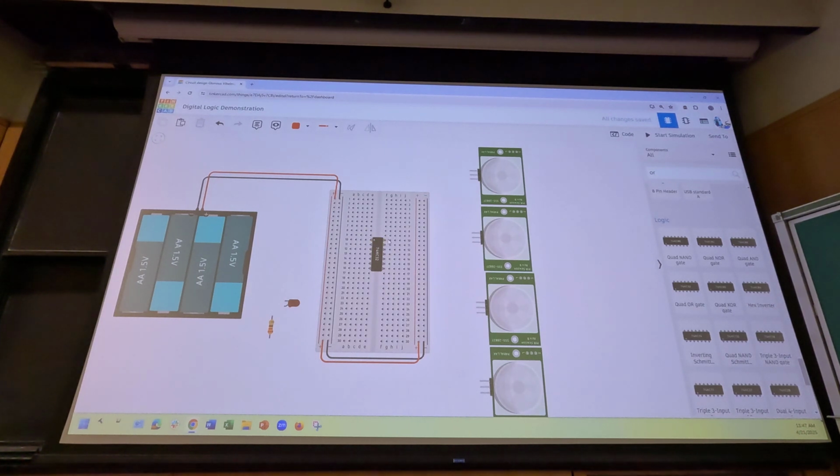So bare minimum, actually this is another one of the things I probably should have checked to make sure this chip will accept 6 volts as an input, but I think it's fine. Okay. Powering the chip doesn't make it explode. So bare minimum for starters, make sure you power the chip. It has those separate power and ground pins, and then figure out how you're going to wire the OR gates such that that LED will turn on if any of the sensors detect motion.